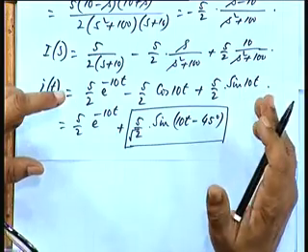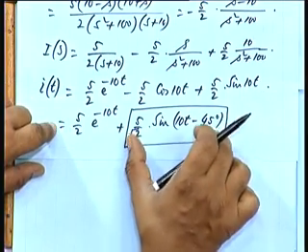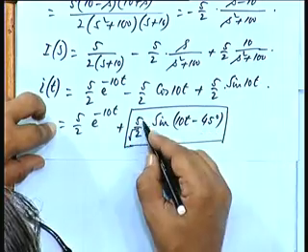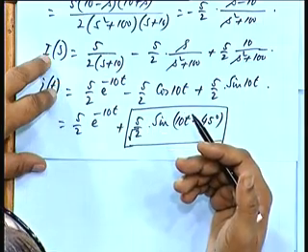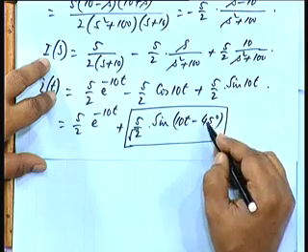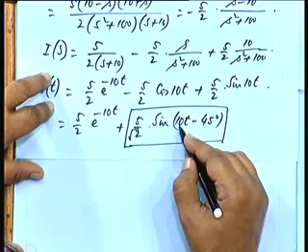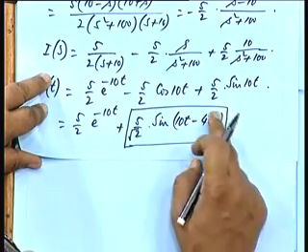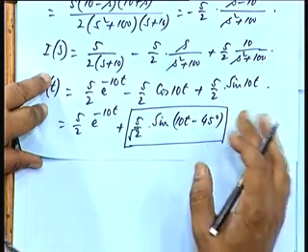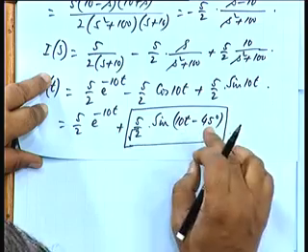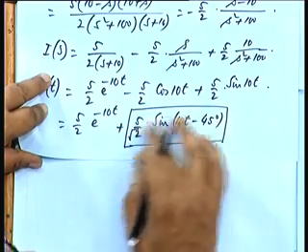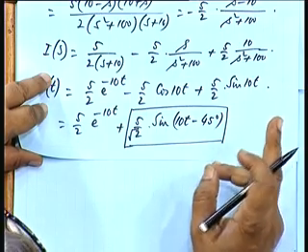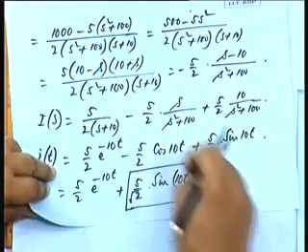Now, when we say we are interested in the frequency response, basically we are interested in the steady state response of the system. As the frequency changes, this amplitude will be modified, and also the phase; this 45 degrees will not remain 45 degrees. If I go for 20 or 30 radians per second instead of 10 radians per second, both this magnitude and this phase will be affected. So, how are these two quantities going to change with frequency? If you can predict that, then we need not go through all these computations.